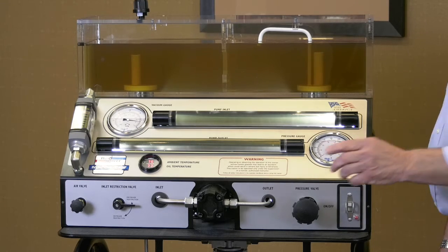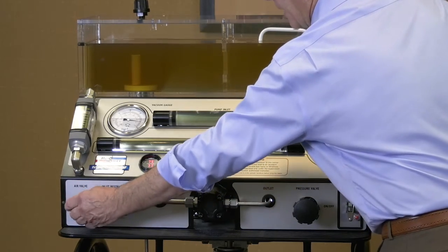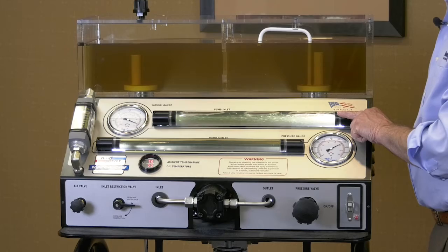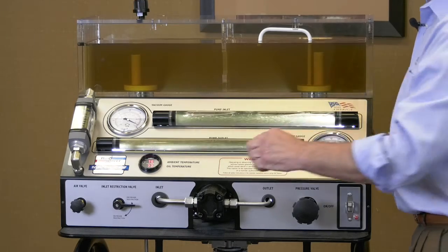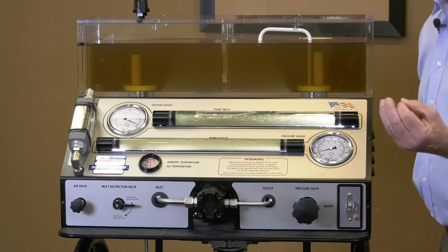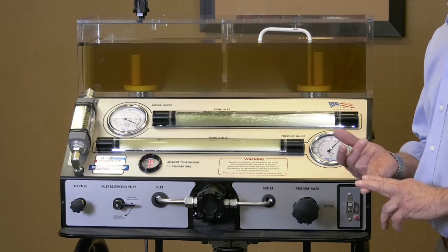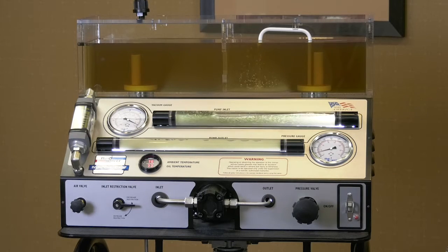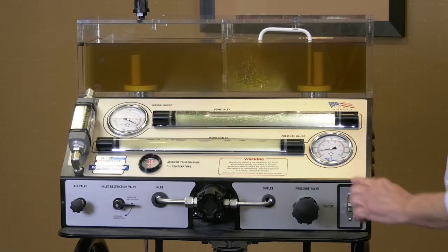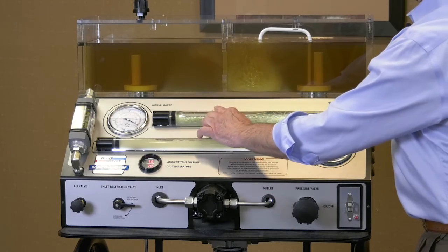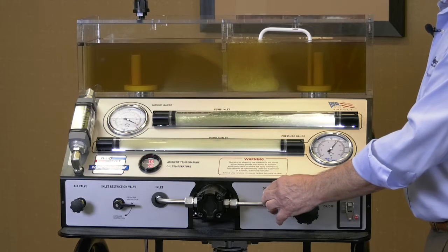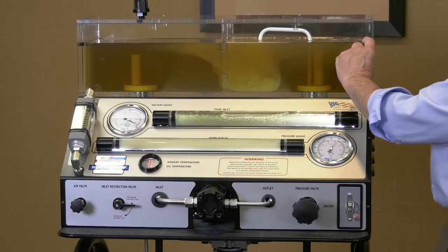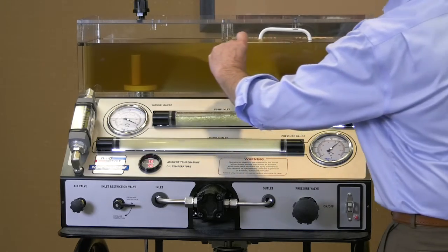All right, so I'm going to open this valve here, which is going to let air go into the inlet side of my pump. So we will see air begin to flow in from the outside. I've immediately dropped my inlet restriction, from a normal of 5 inches of mercury down to 1. This is a systemic catastrophic condition, because now you can see that I am taking air into the intake, pumping the air through the pump, and it's now aerating the oil in the reservoir. So you can see I'm forming a cloud of air across the top of the oil.